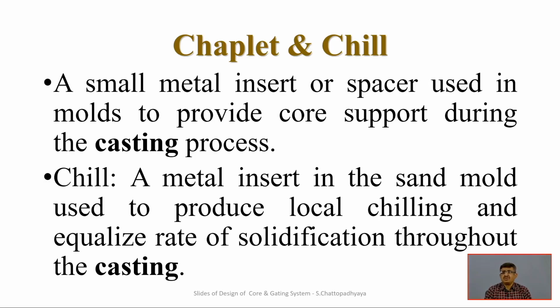So, it is a very difficult process to control all those cooling directions and solidification directions, but chills can give a device, at least for some part of it, where the criticality of solidification, shrinkage, cracking and other things is concerned. Chills are there in order to guide the cooling process in an appropriate way, so that those kinds of defects will not appear at the very, very critical places of those castings.